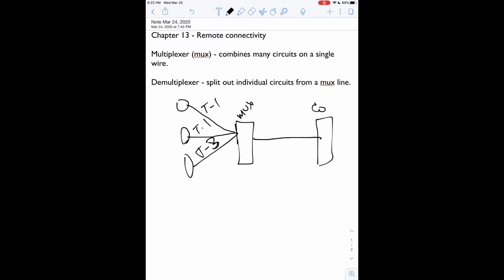So that's how a multiplexer takes all these lines from different buildings, different companies, and puts them all together. This is located in a central office of a telephone company. They trunk them into a cable and send that from central office to central office. In the other central office, they can also run through a demux process, where the circuits now go back out to different facilities.